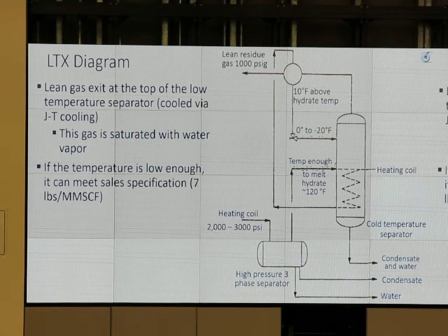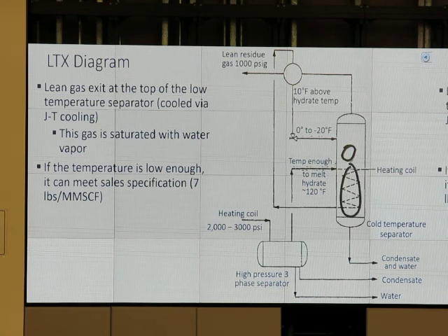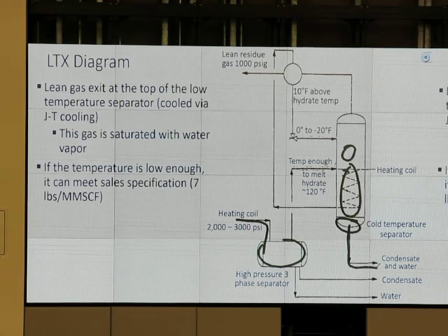We haven't talked about what it takes to get that amount of heat in there. Hydrate forms in the separator, and in the separator we have a heating coil, and heat from the coil comes from the gas stream, right? Because heat from the coil goes to the hydrate, it melts the hydrate. Good. And then we have condensed water at the bottom, so we can remove water and prevent hydrate at the choke at the same time. Seems to be very good, right?